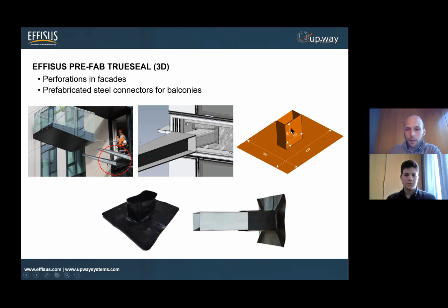Sometimes we are dealing with this kind of width, 120 millimeters, so really small. And then we are able to provide these kinds of pieces that you can just fit into these details. So really easy, no possibility of error. We just need to glue all around this perimeter on both edges of the sleeve.